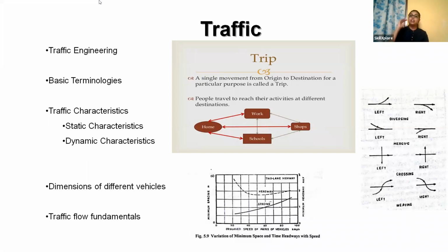And also while we are designing an underpass or overpass, there will be a roof in the underpass. While we are designing a tunnel, there will be a roof, no? So the height of the vehicle comes into play there. So we have to understand the dimensions of the different vehicles. Then other traffic flow fundamentals, many other things which are also considered here. Headway distances, spacing between the vehicles, all these things will be discussed.